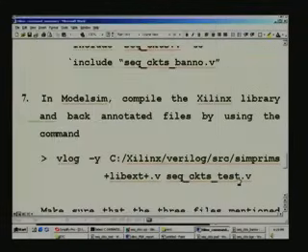And so the next step here is to take this back annotated file and go into the ModelSim and once again view the waveform, see whether the delay has been incorporated or not, right.